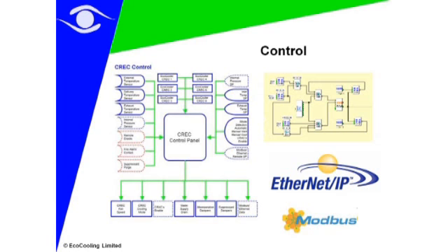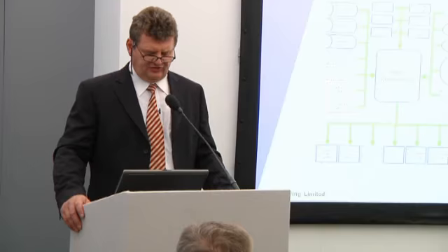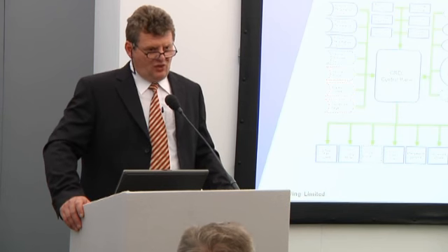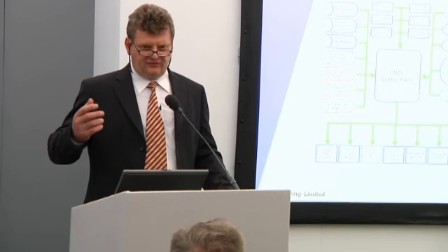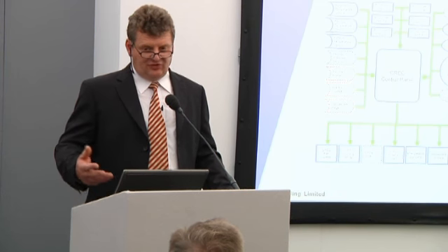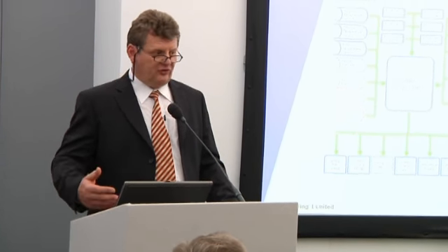We can measure true temperatures and true pressures and true conditions, and that's all linked together with also this facility for either an Ethernet link into your existing network systems, or if using building management systems, Modbus to communicate in one direction all the operating parameters of temperature, pressures, fault conditions, etc. And then as an input, temperature set points, alarm conditions, fire alarms, smoke alarms, fire suppression, purge requirements, etc. All linked together on one common control system.